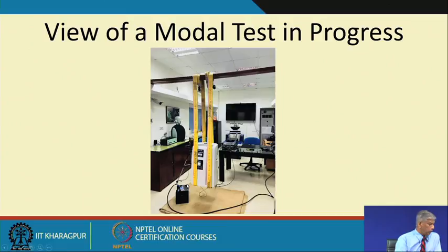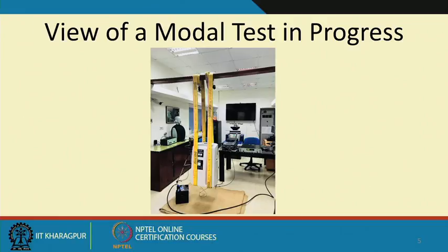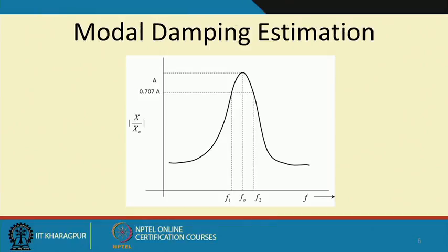In the industry, when we do not have such a system, people resort to what is known as a bang test, for the obvious reason that the autocorrelation function of an impulse response is an impulse function, which is a flat response in the frequency domain. That means the denominator is constant. So, whatever response I measure, I just put a bang and immediately I see the natural frequencies by the FFT of the response, and this is very useful in the industry.